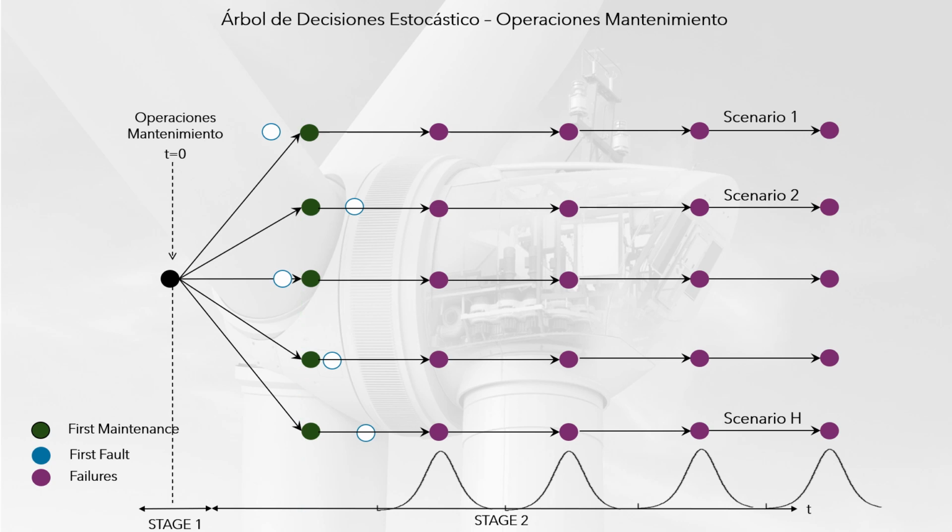If the manufacturer's data is considered random, the future times between failures must be the result of a synthetic failure time generation process. If there are multiple maintenance options, such as replace or repair, failure times must be generated for each maintenance policy, and it would be the mathematical model that, when selecting the maintenance policy, implicitly selects the time to the next failure. This is the function of the mathematical model for complex cases, typical of real industrial systems.